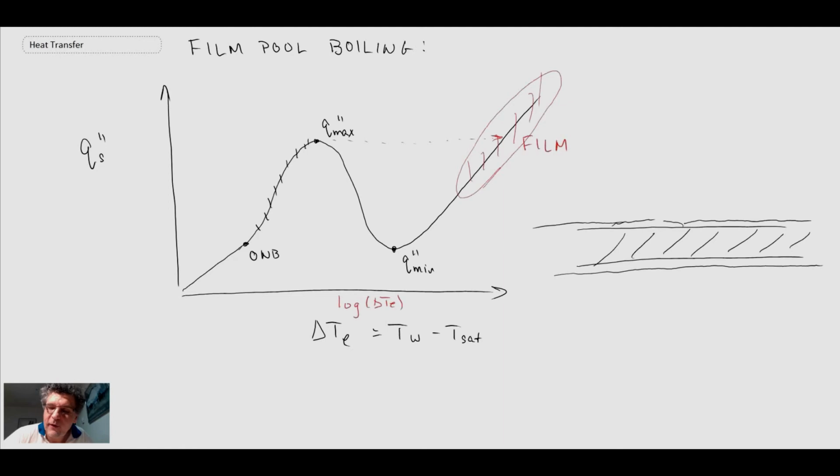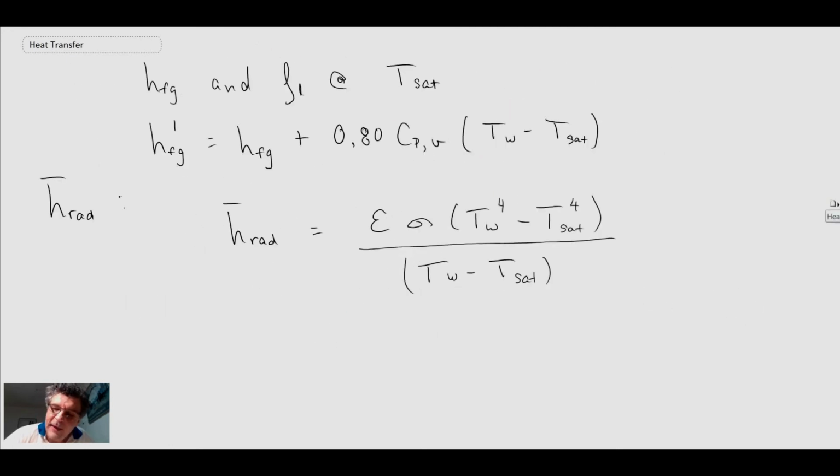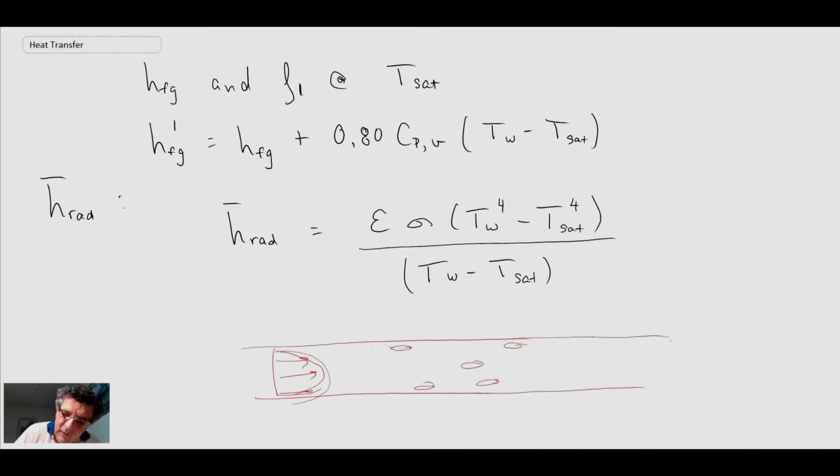Now there is also forced convection boiling. We're not going to cover it in this course because it gets quite complex. You're dealing with multi-phase flow, and the typical one that we would look at would be pipe flow. There you would have fluid flow going through a pipe, but you would start with liquid flow. It would probably be turbulent, but eventually you're going to start getting bubbles forming. And then multi-phase flow is going to go through different regimes,